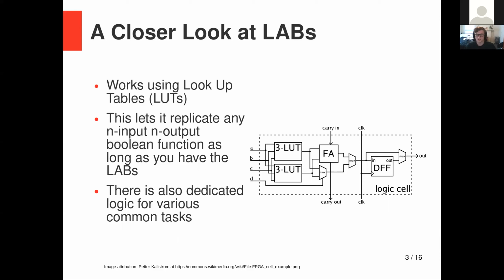They work using something called lookup tables. Essentially, these lookup tables get programmed with a certain mask. It's just a series of ones and zeros that tells them what Boolean function to replicate. So any true-false function. So any n-input, n-output Boolean function you can make as long as you have enough logic array blocks left, because there are a finite amount of them.